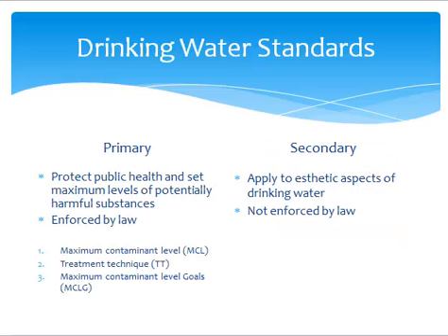As part of the SDWA, drinking water standards have been divided into 2 parts. The first, or primary standards, are those that have to do with public health and are enforced by law. Secondary standards have to do with aesthetics and are not enforced by law. For the primary standards, let's look at 3 divisions: maximum contaminant level, treatment technique, and maximum contaminant level goals.